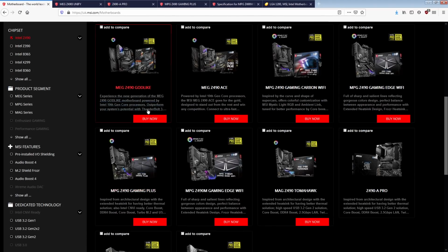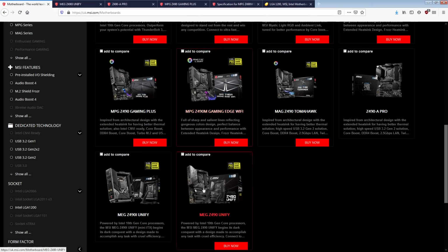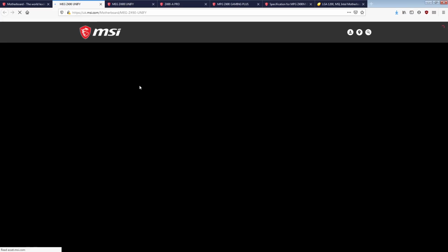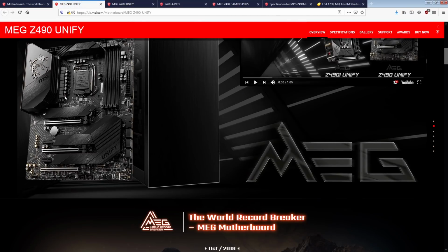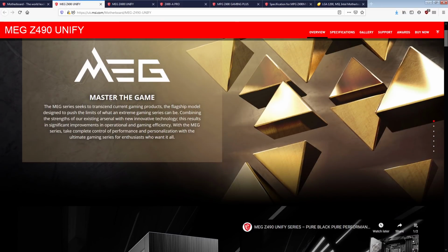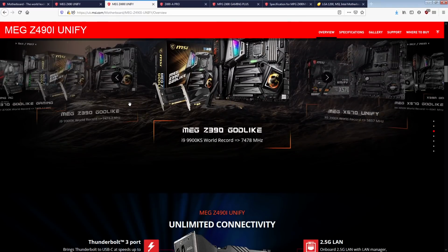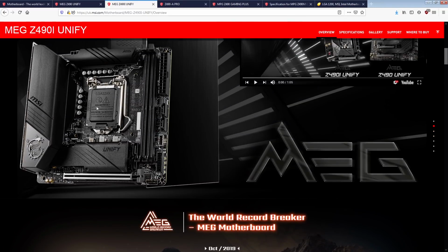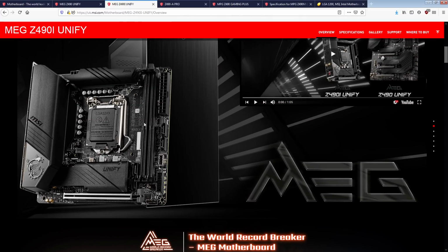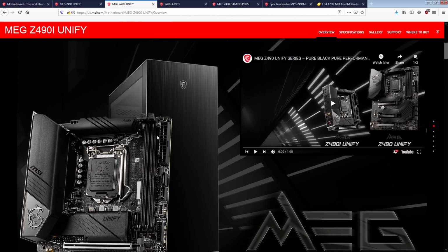And if we compare that to something like, well, let's check the ATX Unify, right? Oh, it looks like MSI is just doing 8 everywhere. So that might actually work out. The thing is, if this loses on anything, I'd assume it loses on overshoot. This VRM is probably going to have more overshoot than some of the other boards. They could still keep the undershoot well under control, but we'll see. That is one thing I definitely want to test. But memory overclocking wise, this should be one of the best boards you can get.